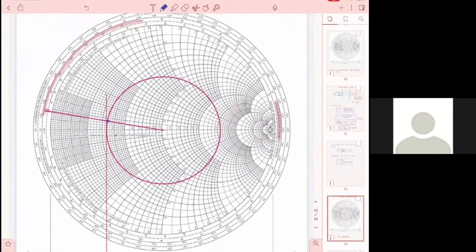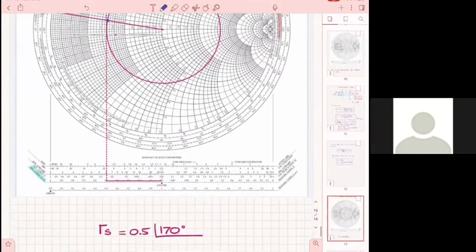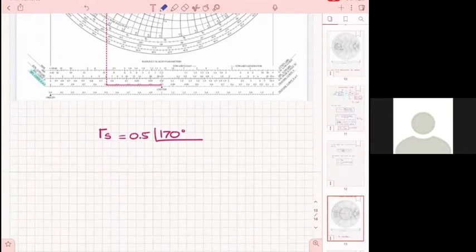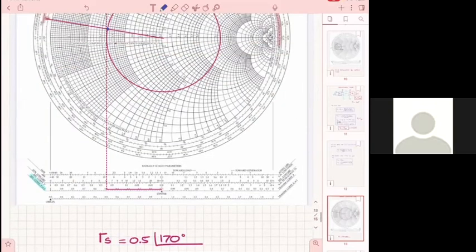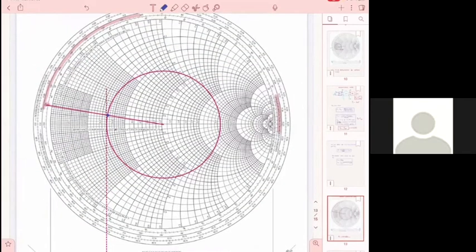where do I need to go with the match? I'm in the matching network. How does the matching network look like? The input matching network. It looks like this. My input matching network is this one. Here I have a 50 ohm. And then this is where I am. And now I'm going to design this so that my input here, reflection coefficient gamma S, is this point here. That's my gamma S, all right?